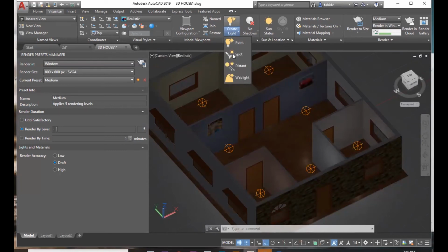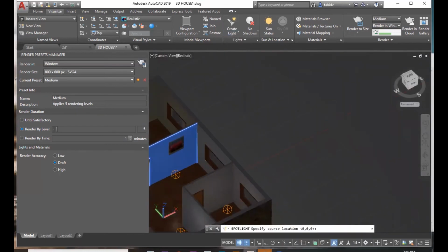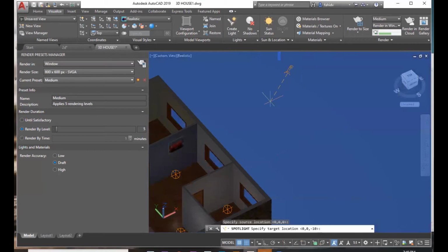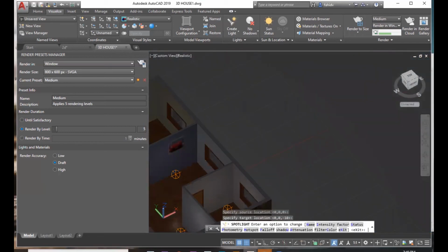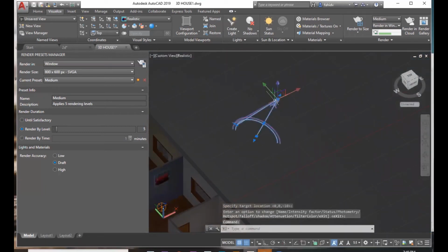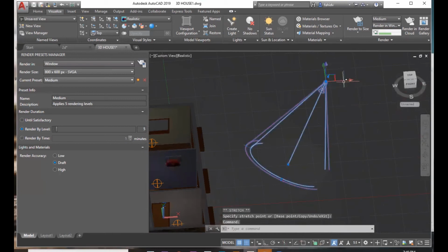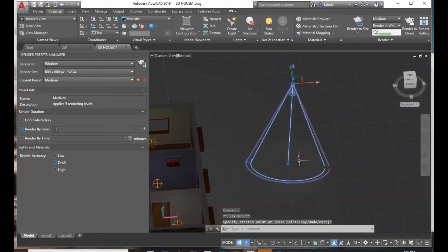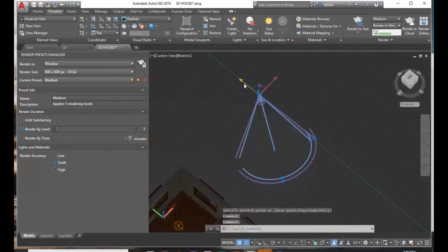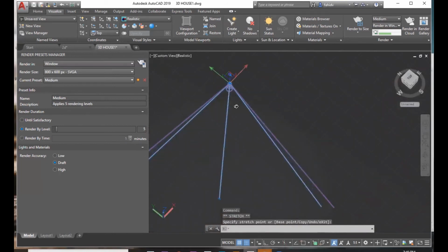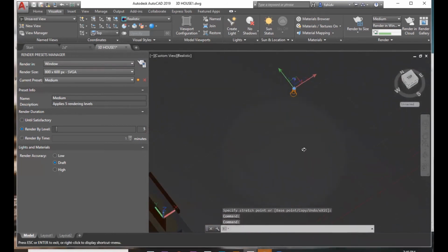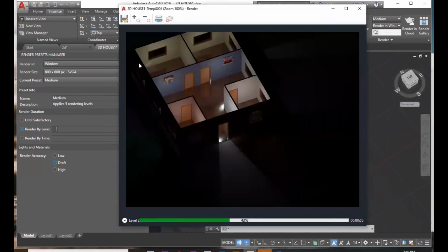Now, if I want to do a spotlight, again, switch off this one, ortho and all. Then create spotlight. Click a point, then you drag it. Enter. See what I did? Select this one now. When you move up, you understand. See, there is a spot now. For this light, there are two controllers: one is the light and one is this aim point.